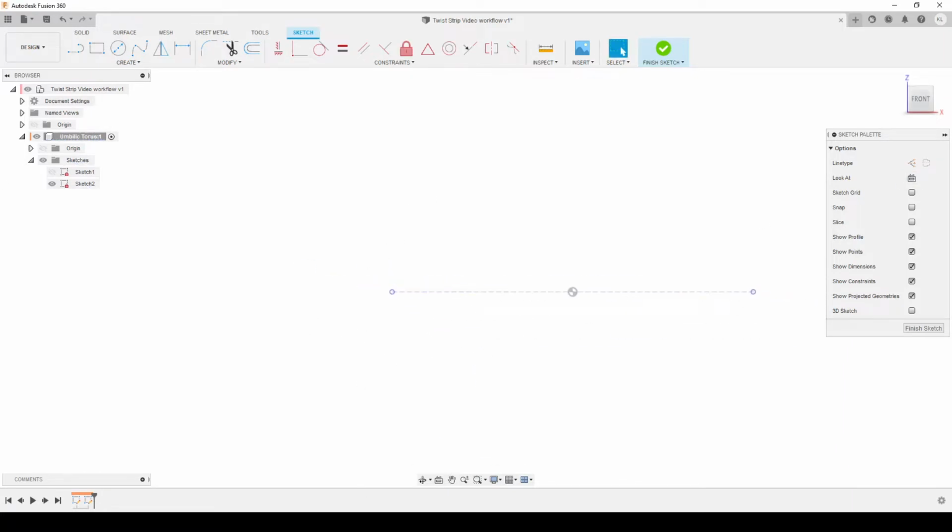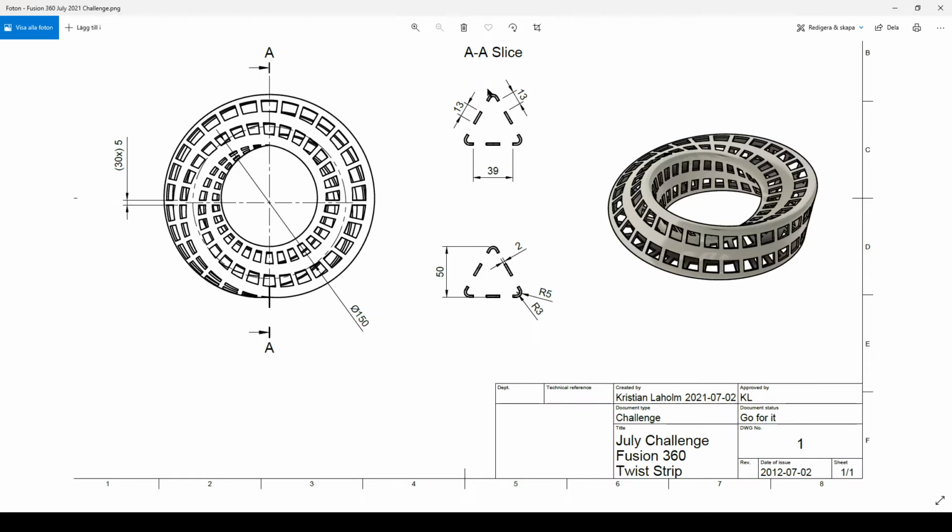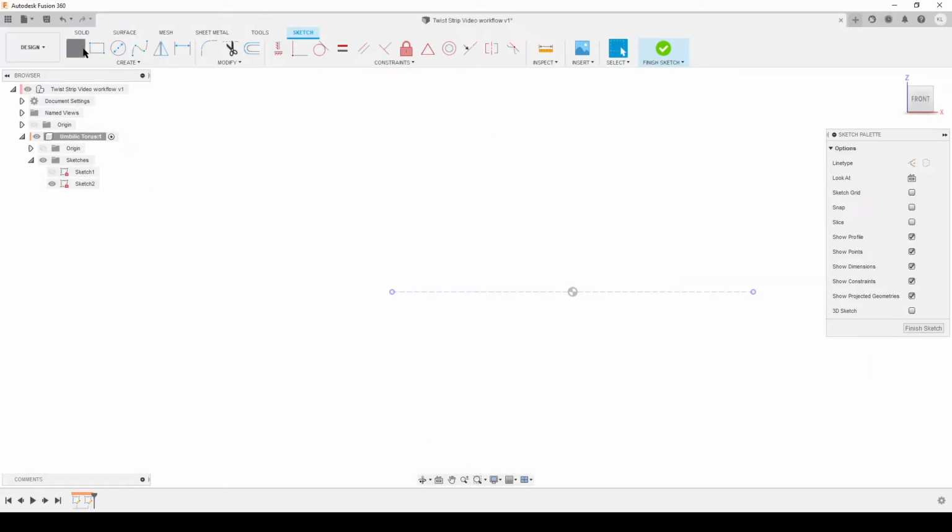Now create the triangular shape here. I'm going to create the outside. There are different ways to do this. The easiest way, best, I don't know, but the way I like is to use line commands combined with arcs, which I do by starting a line, holding down the mouse button, and doing an arc. Every time I do a sketch, I try to find where it gets tangent, not parallel or anything. It saves some work adding tangent constraints. You can see I got tangent constraints everywhere except one, so I'm going to make this tangent.